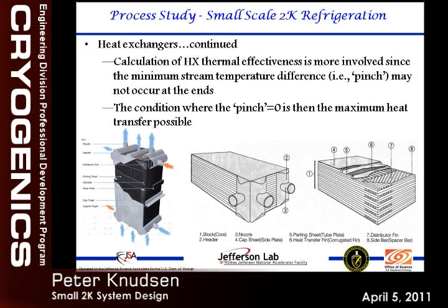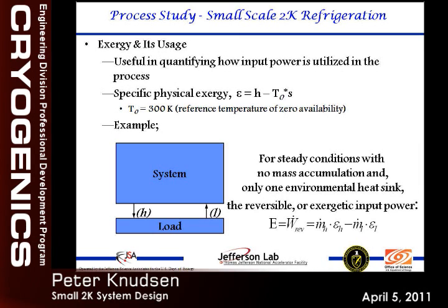Like your budget for your house, you should be able to subdivide where everything is going: what component, how much power each component is using. That quantity is here. The exergy is equal to enthalpy minus a reference temperature, typically 300 K, times the entropy. It's a physical quantity.